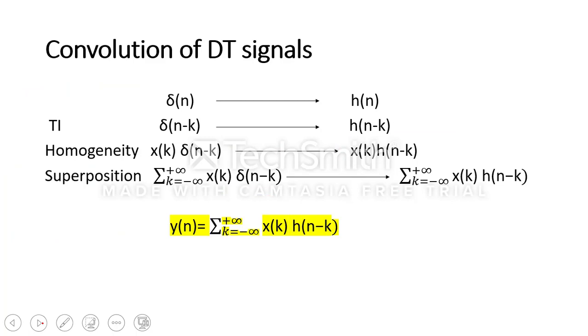Now coming to convolution of discrete time signal. As we did for continuous time signal, in discrete time signal, instead of t we take n, because in discrete signals a number of samples are present. If an impulse signal is applied, the response will be the impulse response. And convolution we always find for a discrete LTI system, that is a linear time invariant system.